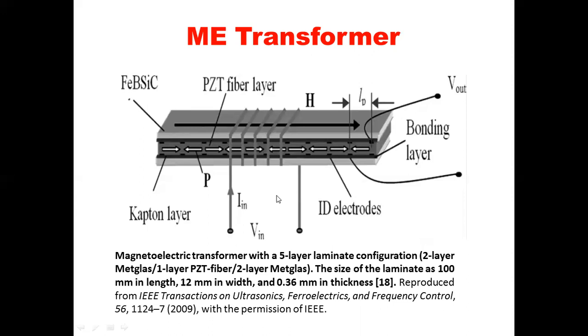It is a 5-layer device. The 5 layers are laminated one over the other: 2 layers of metal glass, 1 layer of PZT in the middle, and again 2 layers of metal glass laminated on top. The size of this device is seen here.